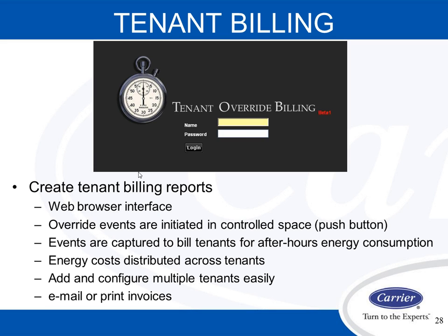You can do simple things such as after-hours energy consumption, assuming you have the proper devices on the network. So if they hit the push-button override, maybe included in their lease is normal business hours, Monday through Friday. If they hit the push-button override after normal business hours, or on a Saturday, the tenant can bill them depending on their lease.